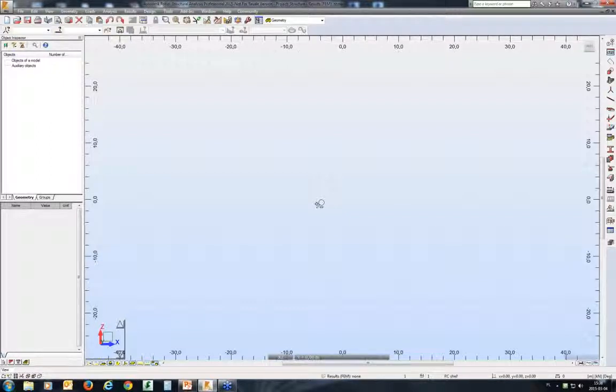What I would do is create this simplified frame model, look at the diagrams for bending in a beam and check what is the value of bending moment at the edges of the column. And then I would make a couple of simple slab and wall models with different sizes of meshing, and compare which size of the element gives me similar results to my frame model. But from my experience, that's usually something between half of the size of the supporting column to the size of the column for element size for meshing. I would try this sort of settings.